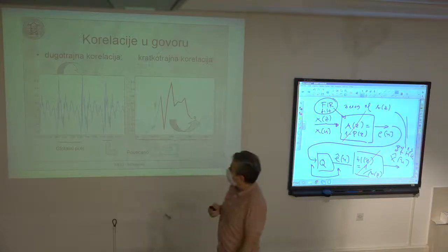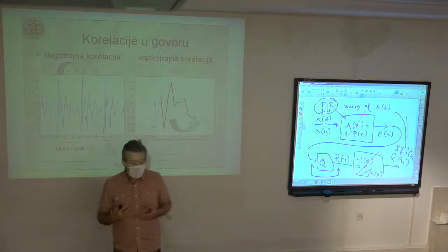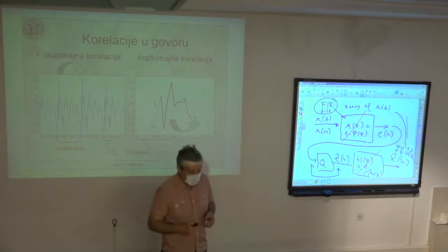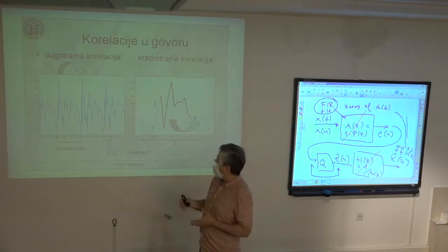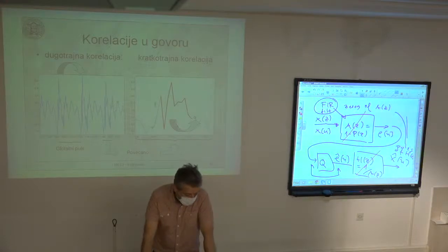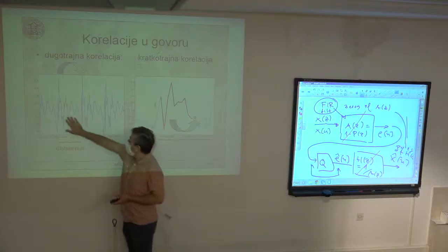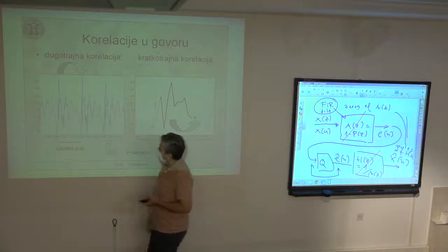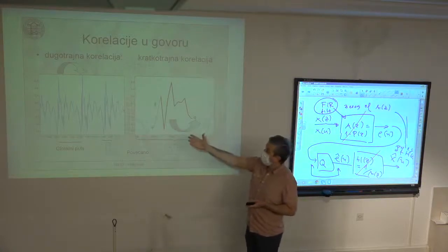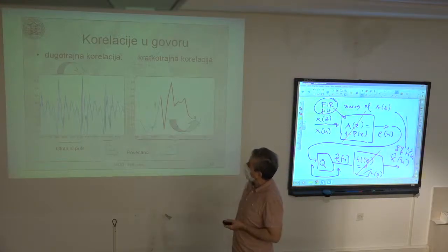And in this case, the vocal folds are not vibrating, and the excitation in the case of unvoiced sound is more or less like a random noise, as if the vocal tract is excited with a random noise signal. If the consonant is a voiced consonant, then the excitation is a periodic excitation. Okay? So this is the case for this voiced sound, where I have the periodicity of the excitation signal, and this basic or fundamental period defines the lag, the delay between two neighboring periods.